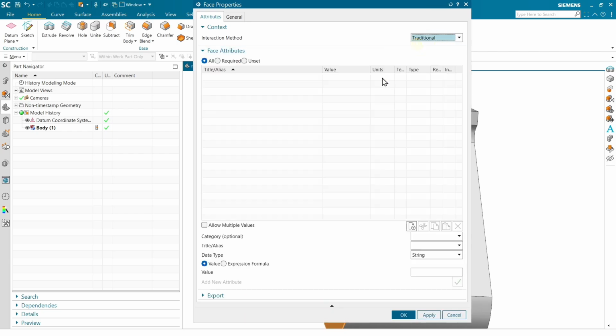I'm going for traditional, and there's a title here. You have to be cautious, you have to write it, it is case sensitive, so you have to write it that way. And I am applying load phase, and giving ID 1. You have to give some random IDs, and for some reason you have to press the tab button, and then this check mark will come, and then click OK.